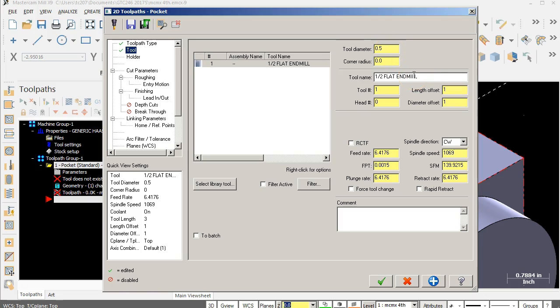All right, so the overhang, the 4 inches of overhang, we're going to have some additional vibration. We're going to have some additional harmonics to contend with. So until it gets out to the machine, and we're back to that observe and react thing. Until it gets out to the machine, I'm taking my best guess on speeds and feeds.